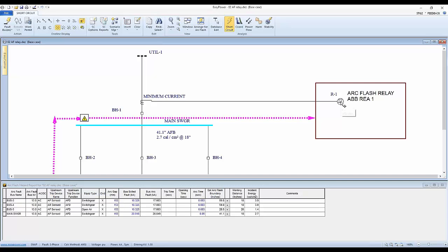There's an option to have a relay sensed or a CT sensed current level that enables the function, so that you don't start getting trips from light that's generated when you don't have the system on or you don't have a minimum amount of current. So at least for my application, that's the way I've done this. There are ways to modify that, I think, based upon your need.